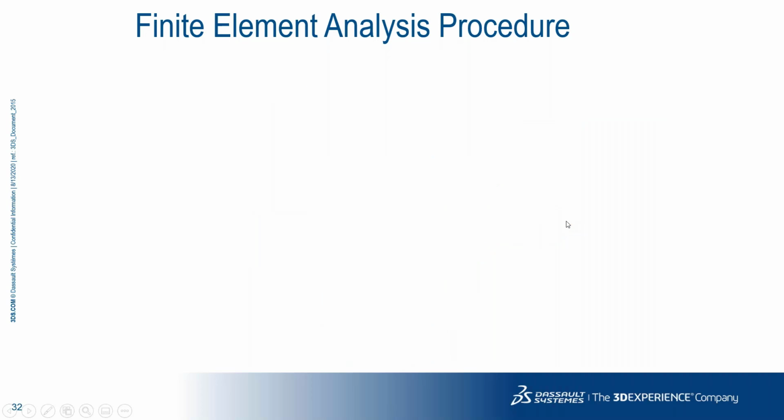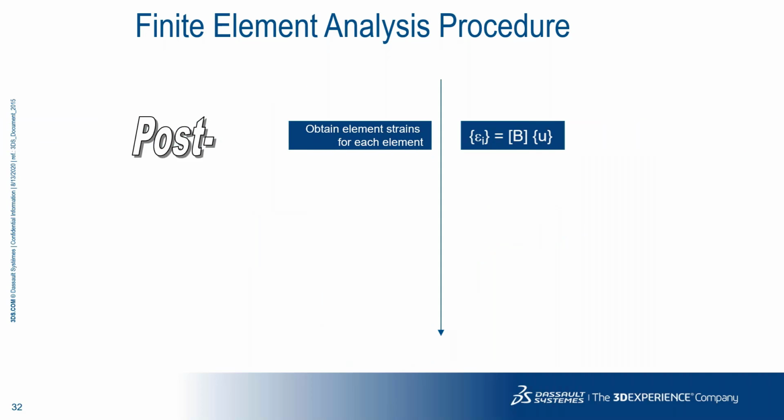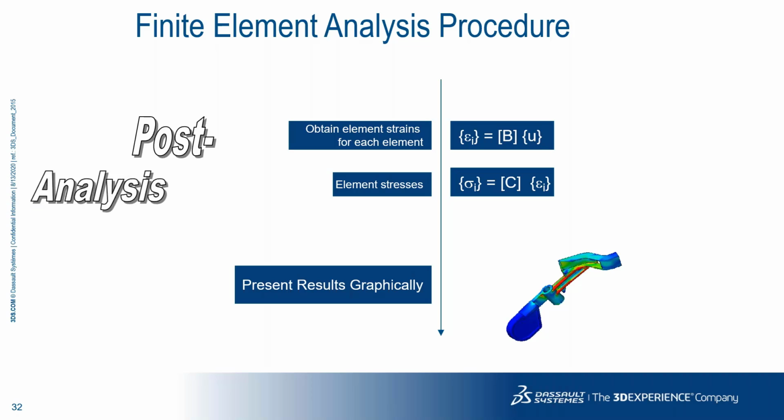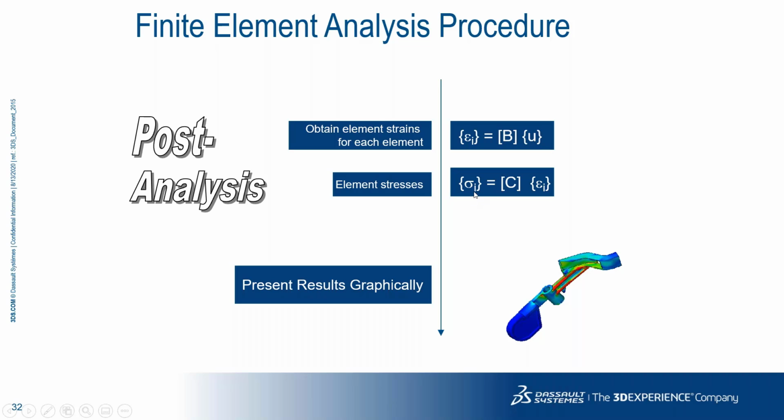Then that displacement we use to calculate the strains. Then finally, we calculate the stresses. So stresses are the final outcome when you perform the analysis. You might use it first for judging failure, but it is the last thing calculated: from the displacement, then strain, then by Young's modulus we calculate the stress results.